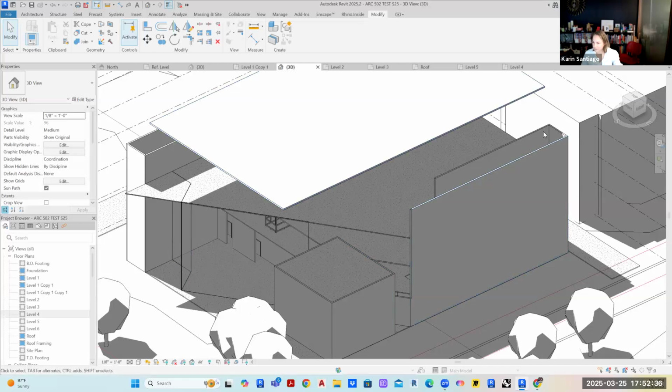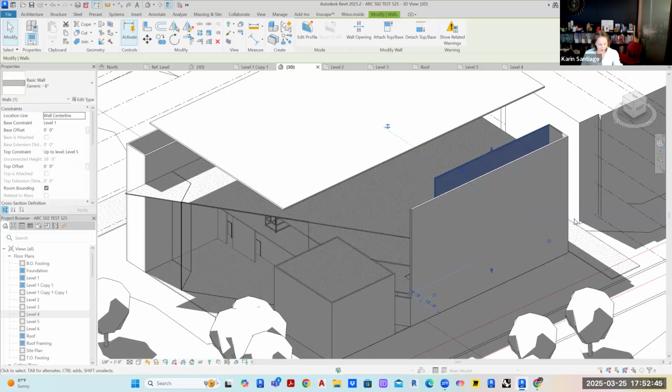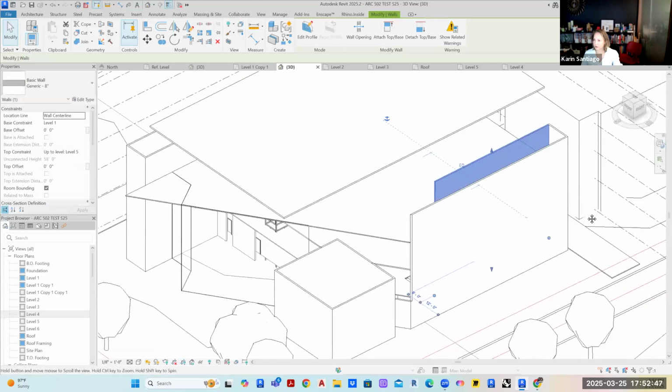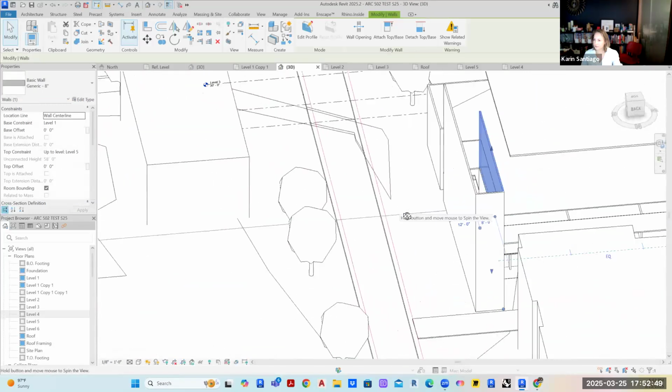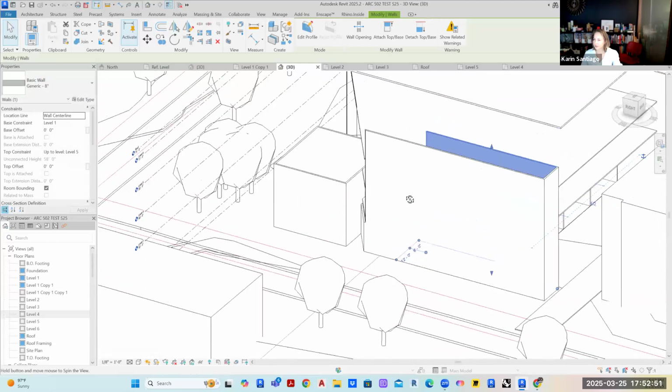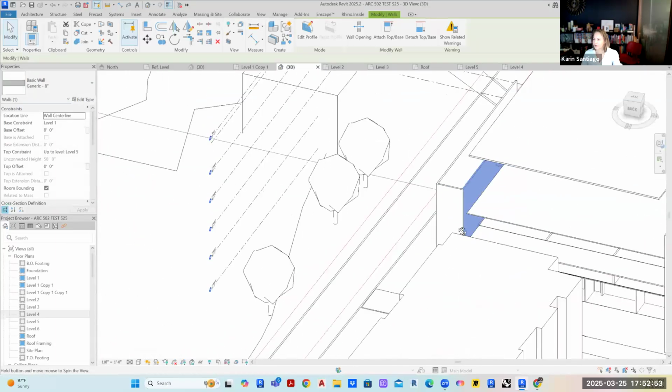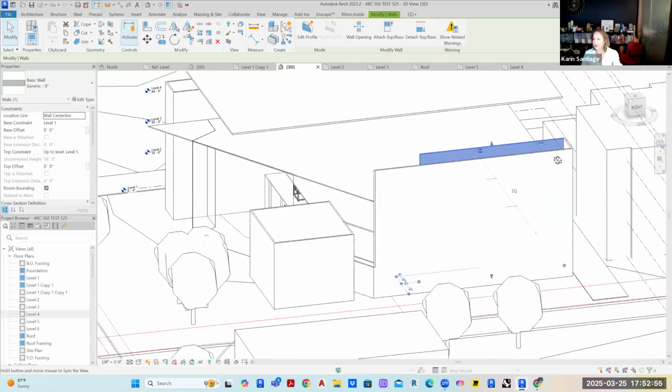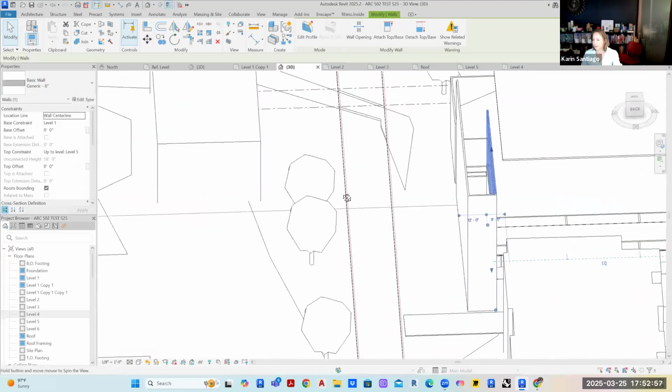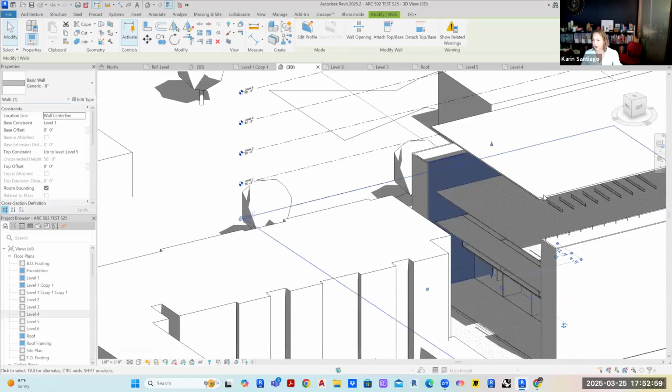So in Revit, when you're moving and navigating around, in case this is driving you crazy, if you happen to click on an element and then you go about rotating your model using this feature, you are never going to lose that center. So it is a really good thing to have.